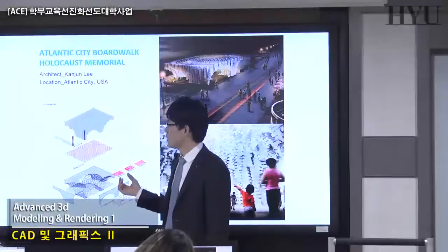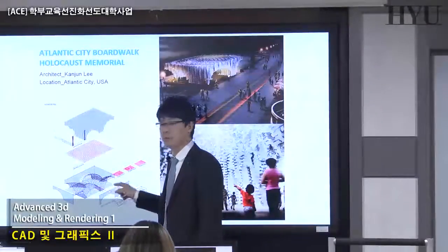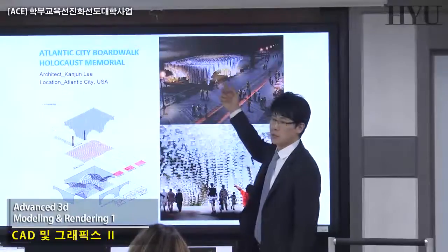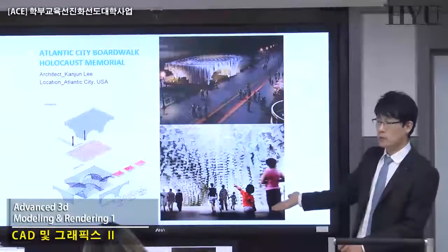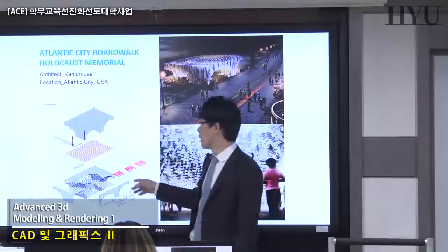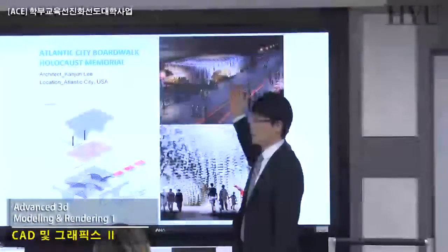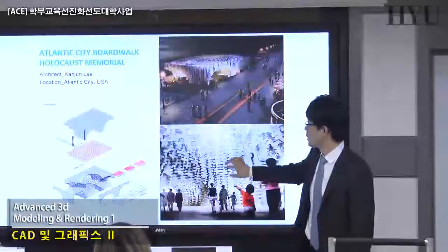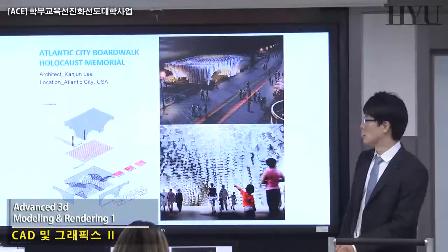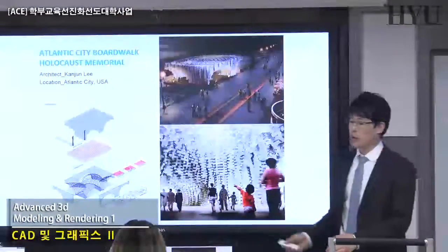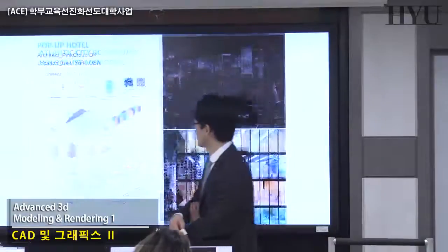But simply Boolean operation, A minus B. In this case, 1 single cubic box minus 4 half-dome cubic shapes. And then you can finally get this kind of void space interior. So from very primitive objects, based on the process, I mean some simple A minus B process, we can generate something like this mesh shape, but that is too simple. So something unique, material filled in this solid part of that mesh, is going to look like this. Anyway, we can recognize the design process, concept, and how primitive geometry can affect the final object in this way.